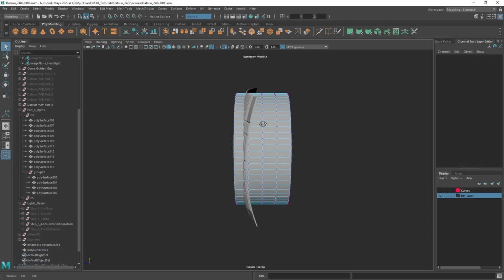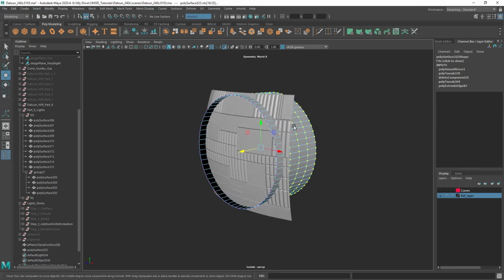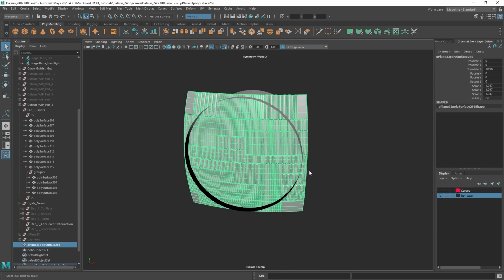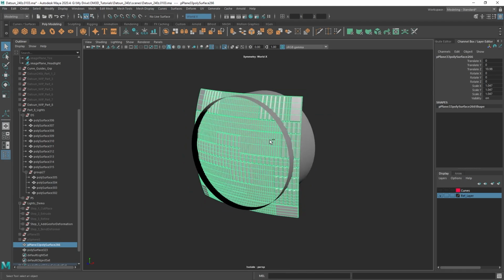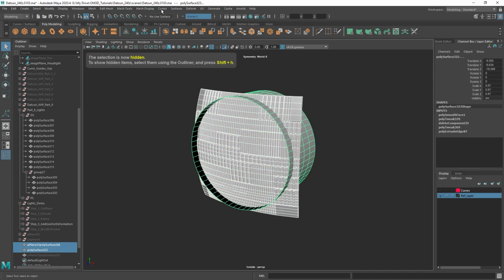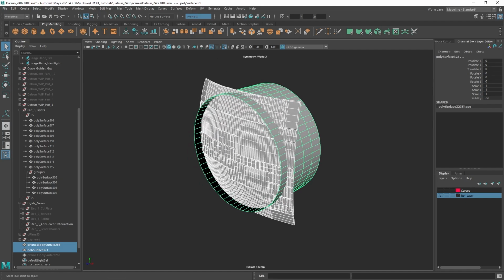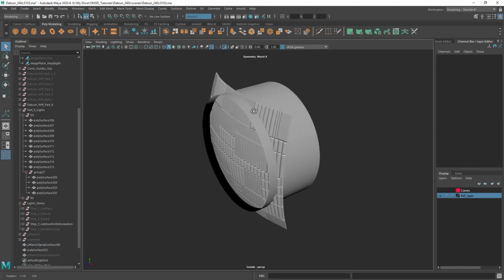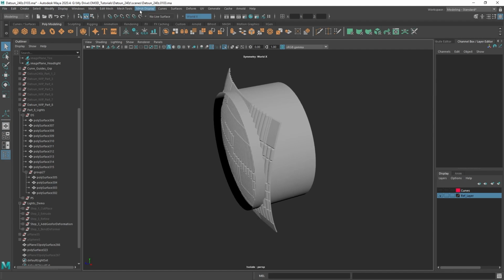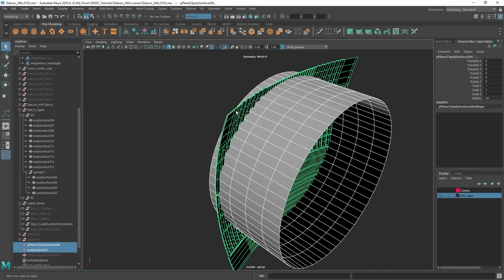And I just want to move these vertices here, because what I can do now is just do a simple Boolean. Now what I would highly recommend is duplicating this piece of geometry, hiding it, taking these 2 pieces, deleting history, freezing transform, make sure everything's clean, and then we can go ahead and do our Boolean. Alright, so the key thing that I need to bring up is that the Boolean tool can be pretty clunky sometimes, and it doesn't like doing Booleans with one-sided geometry.